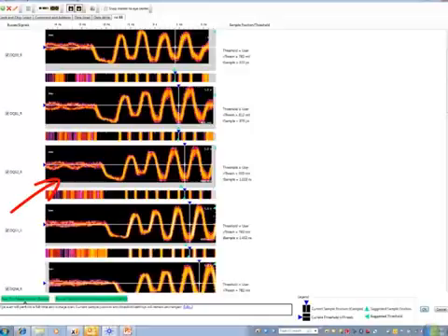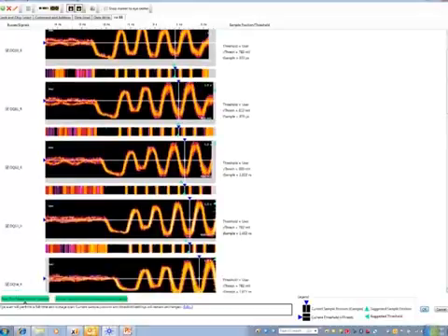On the left, we see the tri-state, then a dip where the strobe goes into its preamble, and then each edge of the strobe is going to clock data in our system. Typically, the bursts are bursts of 8, so we see 8 edges of the strobe. Engineers can view the strobes all relative to each other, comparing them to see if they have similar preambles, similar signal swing, and if the signals are behaving as they expect relative to the clock. The clock will be at time 0.